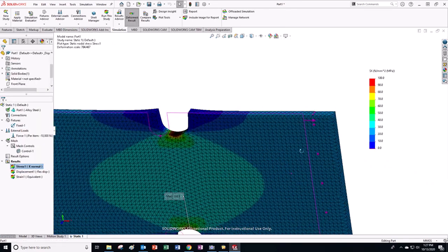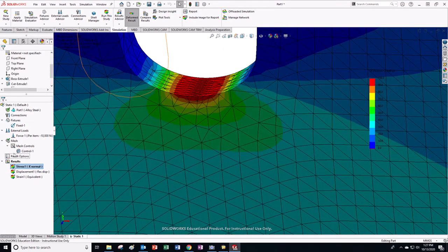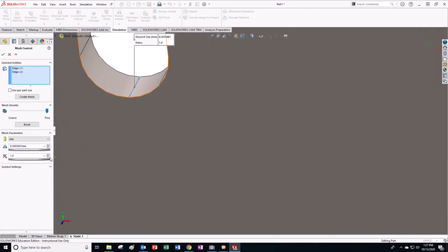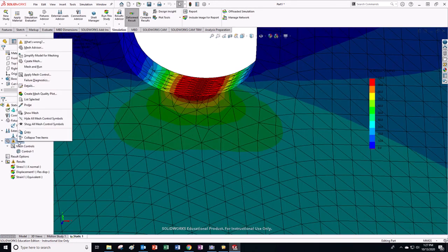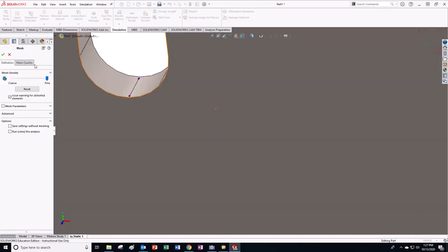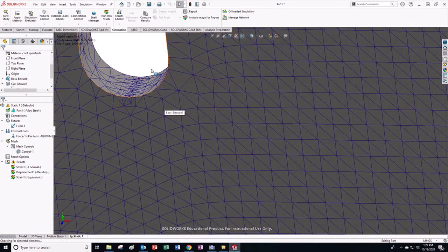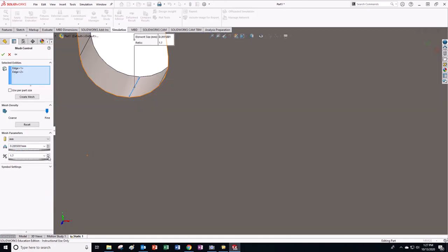And that's about it. I think there's a lot of information right in there. But what you really want to do is, if you can, edit this definition of this control, and I think going down or maybe going up. Let's try it with up. I think that will make the number of elements. And by the way, sometimes that makes the thing so it won't mesh. Warning you. Yeah, so that went the wrong direction here. I always forget. So I think I got to go down.